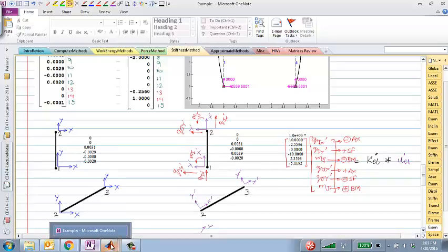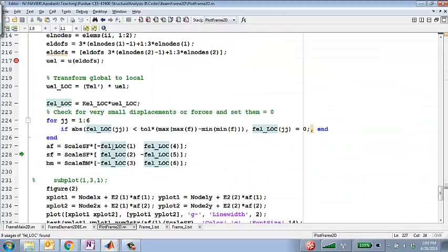Which is exactly what the MATLAB code also does. It takes the first element, negative of that gives me axial force at node 1, and F element fourth component is Qjx prime, and the positive of that would give me axial force at the second node of that element.